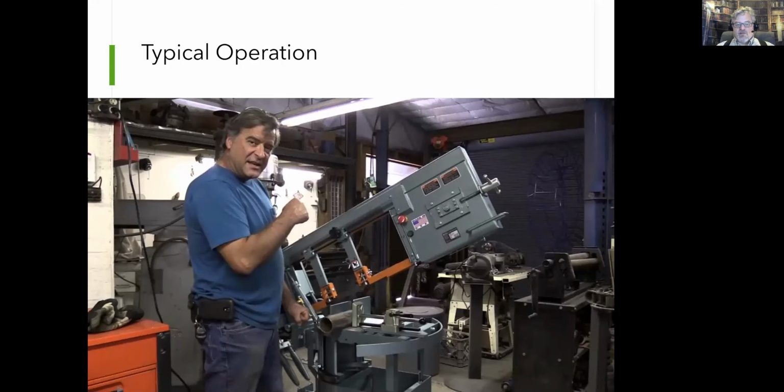This is a very typical manufacturing operation. That guy is a typical manufacturing guy. In this operation, you have a piece of stock that gets clamped in. As you can see, there's like a clamp down here. Here, let me turn on my highlighter, laser pointer. All right, see this clamp down here? That clamps this round stock in place, and then this giant saw, there's like a blade right here. You can't quite see this blade, but there's a blade that goes around a big oval. And when you drop down this whole saw assembly, it chops off whatever steel material is inside the clamp.